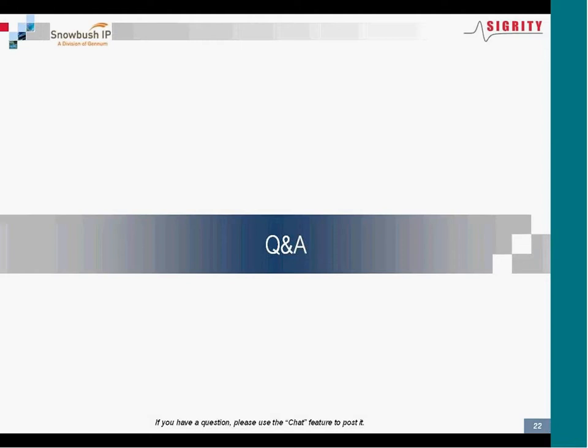So what we did is, we wanted to carefully make sure that we didn't exclude the ability of customers to use whatever tools they choose to use. So in this case, they can simply turn off the back channel capability, and they can use the Snowbush AMI model kit in standard IBIS AMI mode, just like all the other SerDes models that are out there today in AMI format.